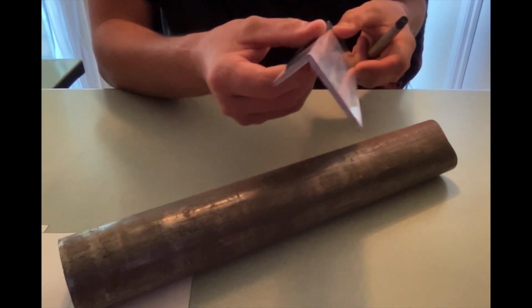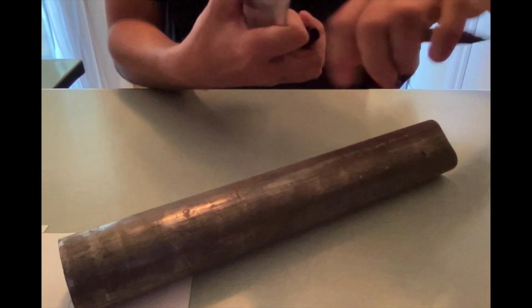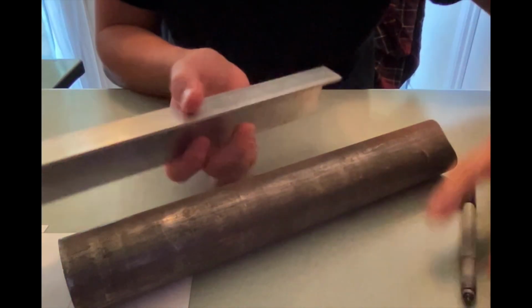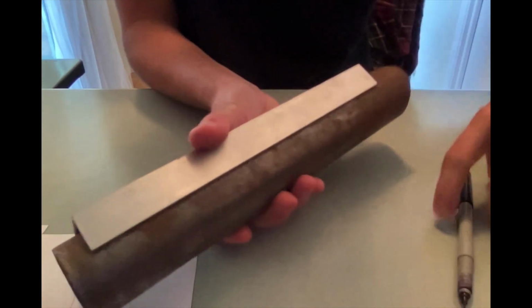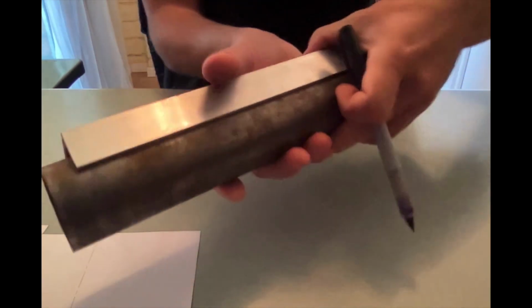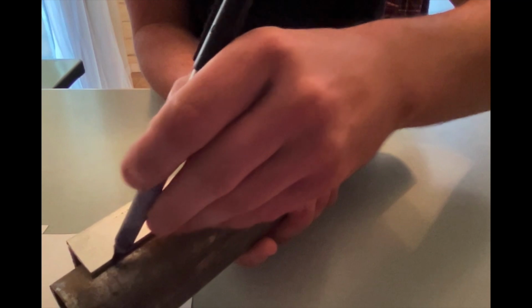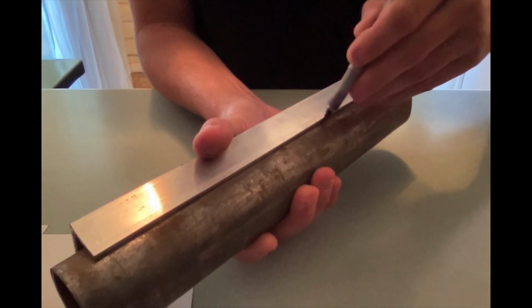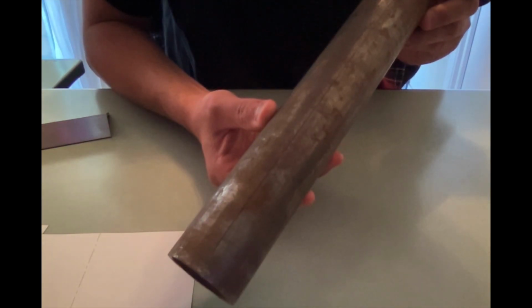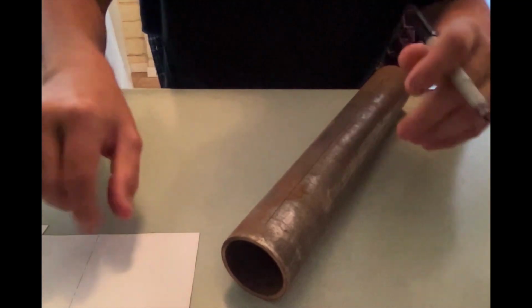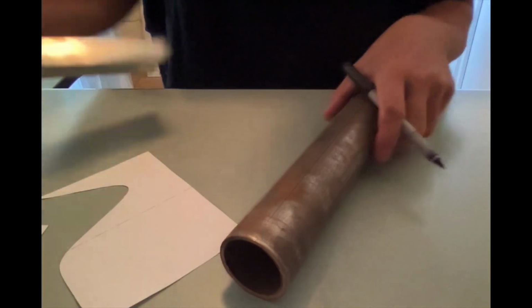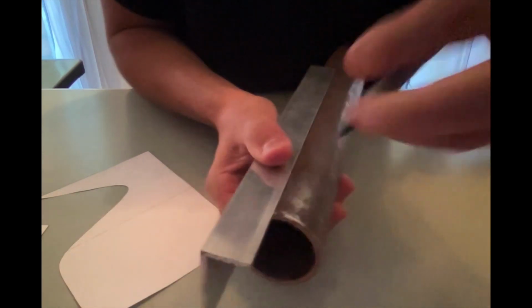So a way that I like to do that is just getting a piece of angled material and then getting a Sharpie, and putting it on our material just like that, and just holding it by hand, and then taking the Sharpie, just running it down that one edge. So now, I don't know if you can see that, we've got a straight Sharpie line going down the middle of our tube. Make this a little bit longer so I go all the way to the end.